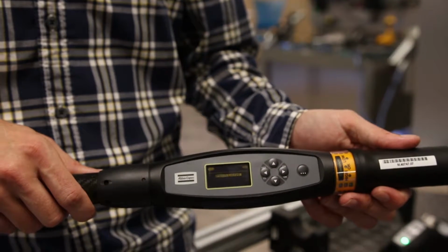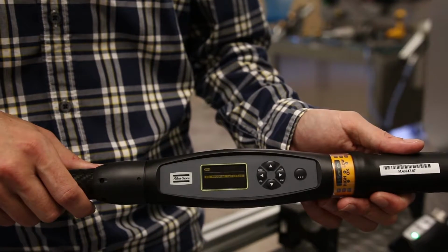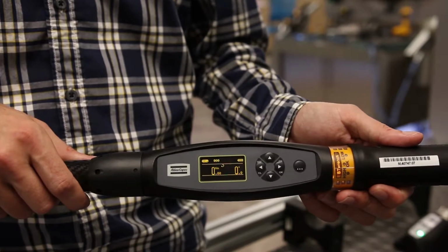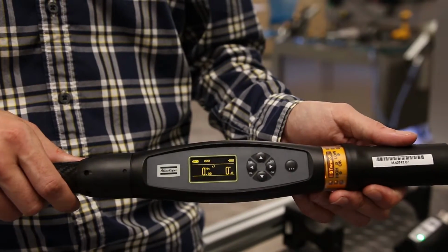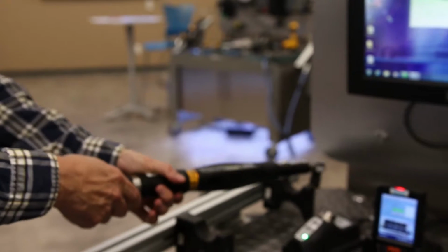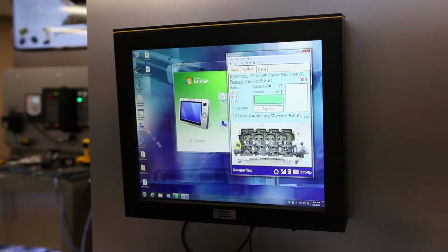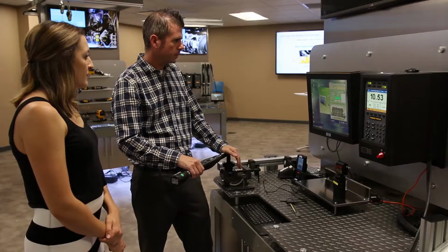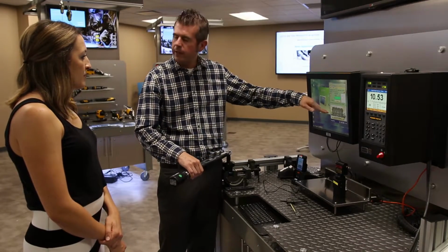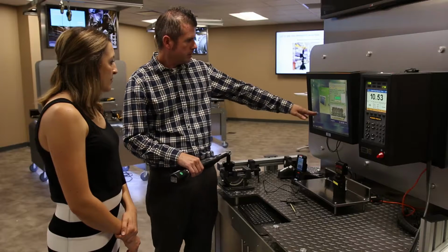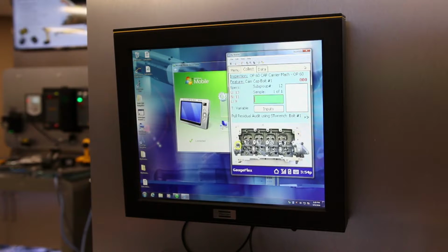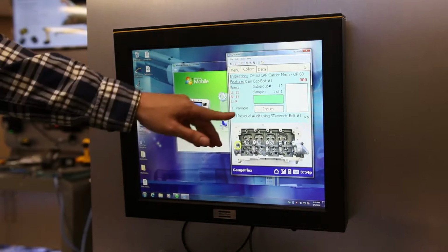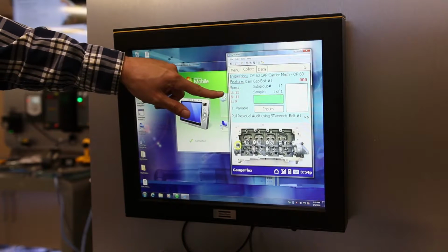Once the inspection is open, the ST wrench will beep twice and display a torque and angle value, both at 0. This signifies that the ST wrench has established a connection to the GaugeFlex and is ready for use. At this time, the GaugeFlex will also display an image. Take this opportunity to inform your customer that we can import pictures for work instructions. Notice the yellow circle, which represents the bolt we will measure first. Also, point out the inspection name, the feature name, and the current subgroup size, including the specifications.